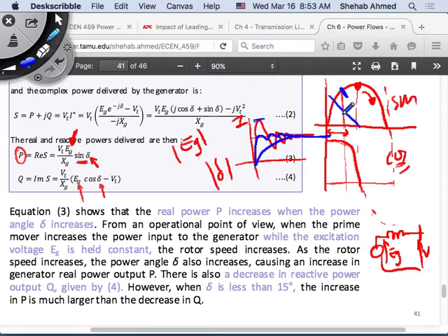So go back to this equation. We saw the relationship between real power and angle before in the power flow equations, when we looked at the Jacobian differentials. Here again, we see the relationship. Angle changes will significantly change real power. Voltage changes are not significant anyway, because they should not be significant.